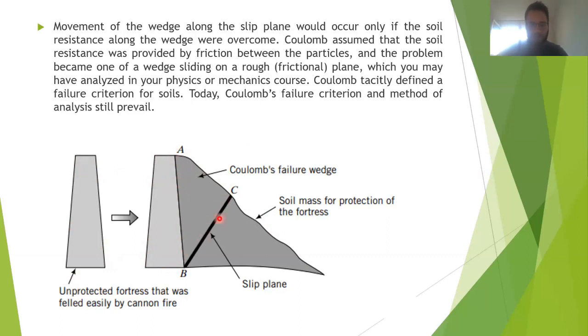Basically, there are a few things that can happen here. First is a sliding surface on the right side, if the slope is too inclined and the force overcomes the resistance of the soil. Another failure is on the left side, where you can have a wedge, and that wedge failure needs to be held by the retaining structure. And that's basically what we're going to do. We're going to first cover some basics and learn how to get parameters, and learn how to actually calculate the lateral forces and how to calculate the retaining structures.